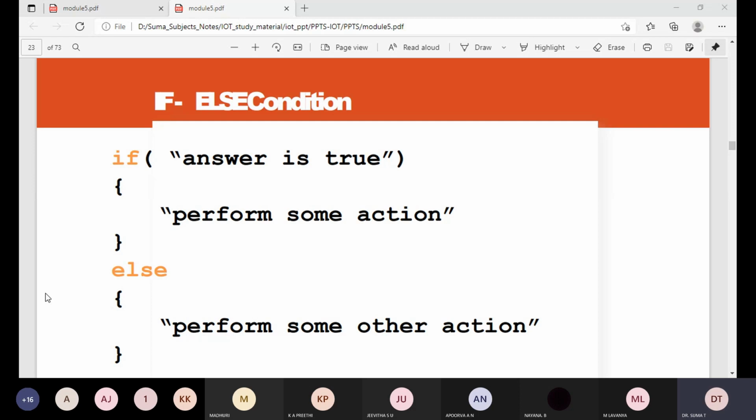In digital pins, you have just two possible states. As I already know, it is represented with a 0 or 1, right? 0 represents off and 1 represents the on condition. These can also be referred to as high or low, 1 or 0, 5 volt or 0 volt. For example, if an LED is on, then its state is high, or 1, or 5 volts. If it is off, you will have low or 0 volt.